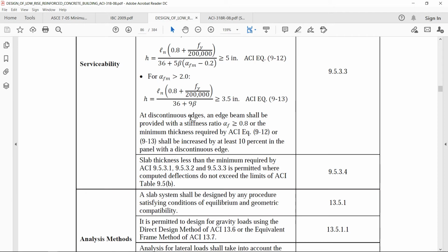Seismic A is very low, no need to do any special thing. But for SDC B, which is a little bit higher seismic area than A, but of course mild seismicity, at least you have to check the proper ductility, structural integrity, and the lap length, etc., so that there should not be any catastrophic failure.